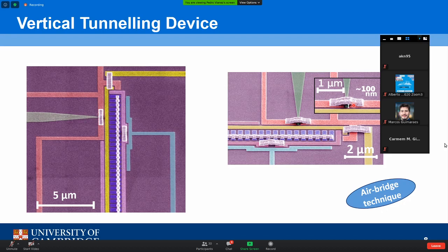So you can see under an optical microscope if the bridges are there. They very rarely break. It's either everything's broken or nothing's broken. And we've been able to fabricate in different devices up to 6,000 bridges in the same chip with all of them connected. And it's a really nice thing to do because, before we had this, we had to come up with very creative geometries for getting this tunneling right and getting the wires around each other. Now we don't need that because we can just go over the gates instead of going around.